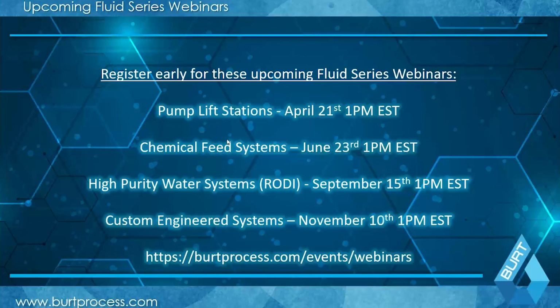What is the requirement for the pump used in the pH system? Pumps serve a lot of different purposes in a pH neutralization system. If it's a transfer pump, it's going to be sized for the flow rate coming into your system. If it's a metering pump, it needs to be sized based on the chemical you're utilizing and the assumed waste of your system, to allow for proper proportional control. And if it's a recirculation pump, that pump's flow rate is not that relevant.